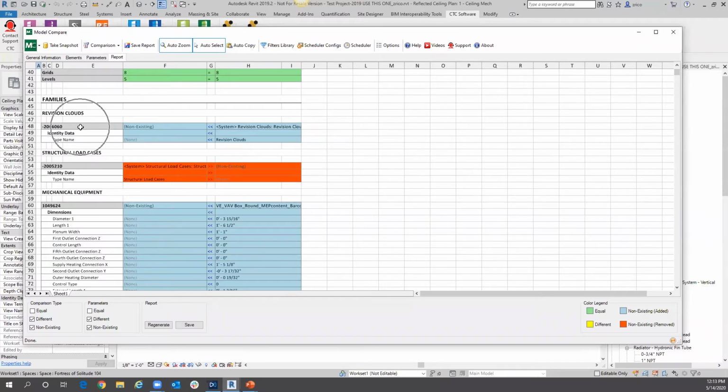What's also nice is it shows me the Revit ID or the type number. So that makes it easy for me to go, okay, this is what it is. A lot of times people are like, no, I don't want the ID number. It's not useful. I don't understand it. Well, I'm sorry, but this is how it goes. The reason that it's better to have the ID number is because every single family and everything else is different. It comes with a GUID number. It comes with a different element. And if you have multiple things that are named the same, it's going to be confusing to read the data and the information. So that's why this is key on all of this.